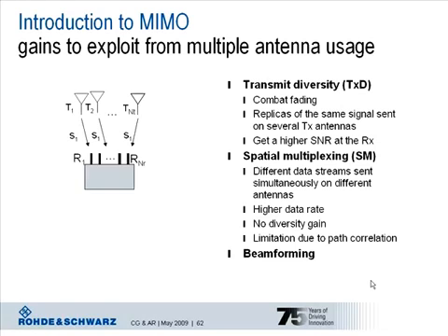By transmitting the same data streams over multiple transmit antennas, for example at a base station site, the receiver, which could be the wireless terminal, has multiple replicas of the same signal available. And so at the receiver side you can achieve a higher signal to noise ratio. This diversity gain is very efficient to combat fading over the mobile radio channel.